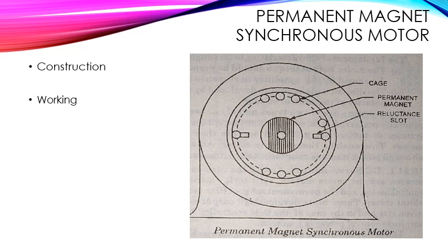Now working. The rotating stator field may be obtained by means of any one of the winding configurations previously discussed, that is, by using the shaded pole or split phase or permanent capacitor construction. Now the permanent capacitor construction provides a two-phase stator near full load, and therefore a uniform rotating stator field is developed and is commonly employed.